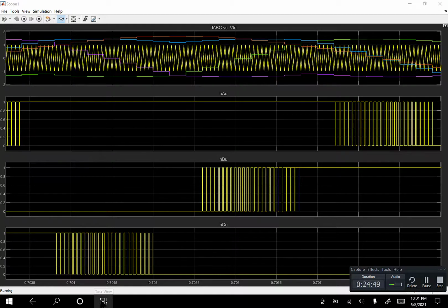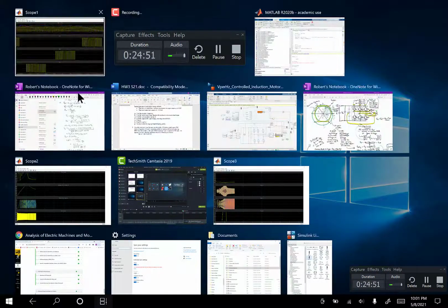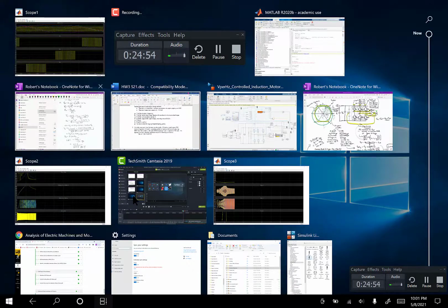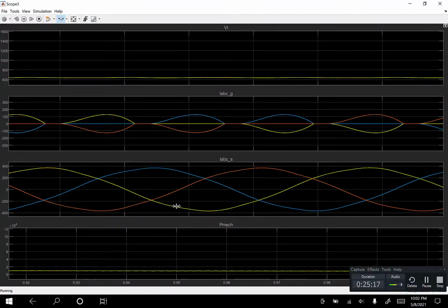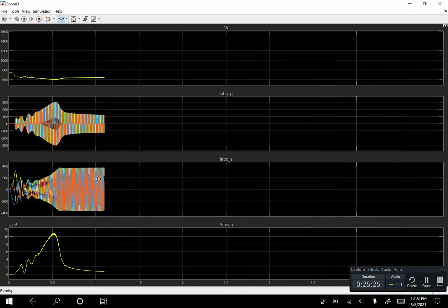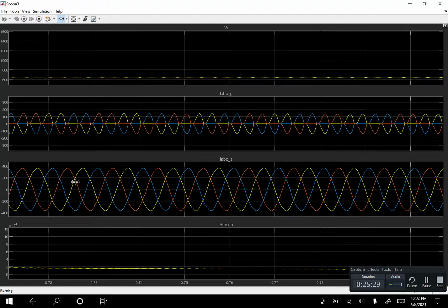What does this actually do to the current? So let's just, for fun, look at the motor. So you can see they're not too bad, but I'm starting to get some low order harmonic behavior. The motor makes a really good filter, but this will introduce torque ripple. You can see how it's getting kind of bent over, and that's because we're in the overmodulated mode of operation.